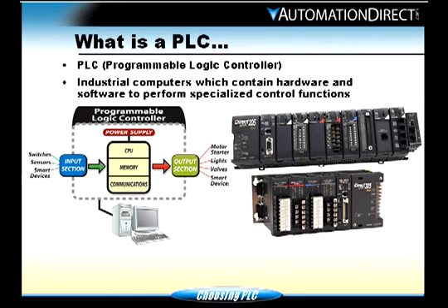Brief example: let's just say you've got a light sensor or some type of sensor, and a box is going down a conveyor. When that box comes across the sensor, you want the programmable controller to do something. Turn on a timer, for instance, for 10 seconds. So the PLC turns on that timer, and after 10 seconds you want a valve to turn on and fill the box full of styrofoam peanuts. So that's what it does. Versus having a person stand there filling it up all day long, you can replace that with a PLC, quicker and faster, and let that person go do something more beneficial.